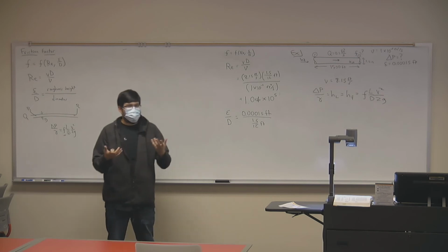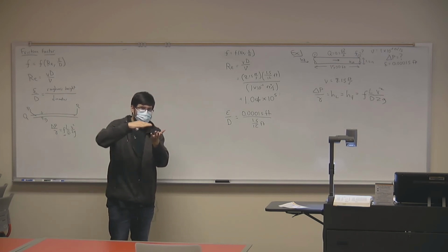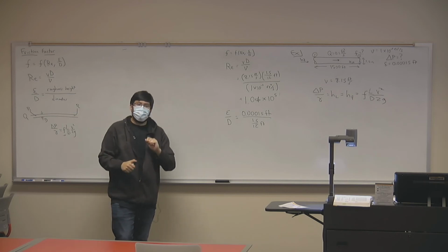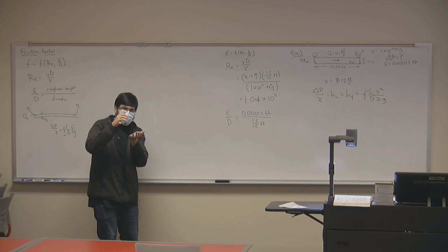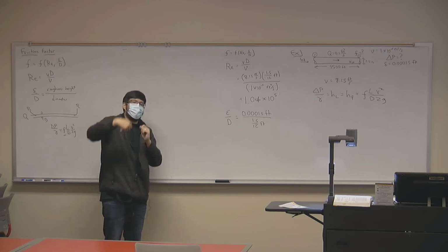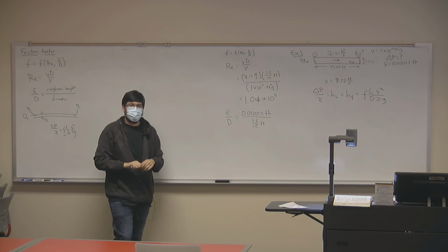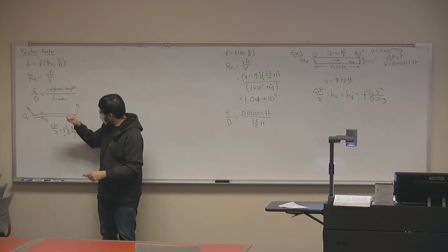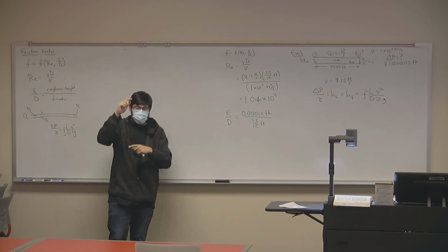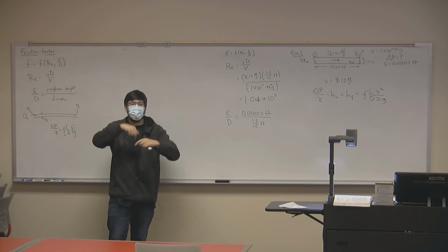They do become rougher. You may think it's the opposite, right? You think, when you use them more, it erodes away those ridges. It's actually not that way. When you use them more, it actually scours. Well, scour is not really the correct word, but it makes the ridges even worse. The flow is turbulent, not laminar, right? So we're dealing with turbulent flow, where fluid particles are just moving everywhere.